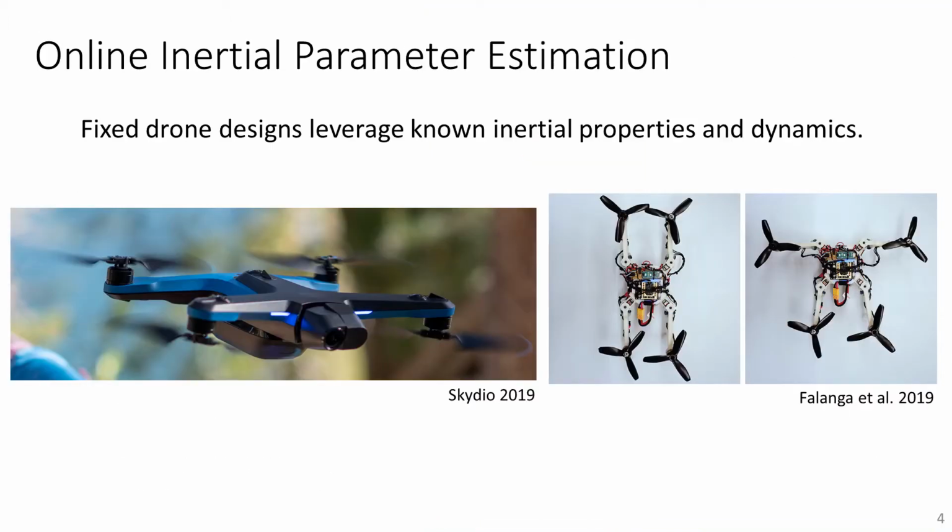Knowledge of the weight, center of mass location, and principal moments of inertia of a quadrotor are fundamental to precise flight control. For a toy or a surveillance drone, the out-of-the-box parameters are easy enough to determine offline. Even for a reconfigurable drone, the center of mass location and inertia tensor are no longer constant, but we might be able to cleverly recompute them online from known design kinematics.